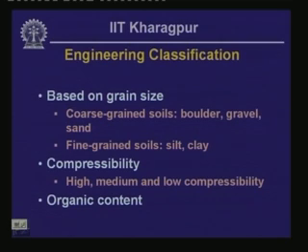Clay minerals are going to be driven by the stickiness or plasticity that develops because of the interaction of electrical nature between individual soil grains, while non-clay minerals derive their strength from the packing or interlocking of individual soil particles. So the behavior of soils composed of clay minerals will be different from the soils composed of non-clay minerals.